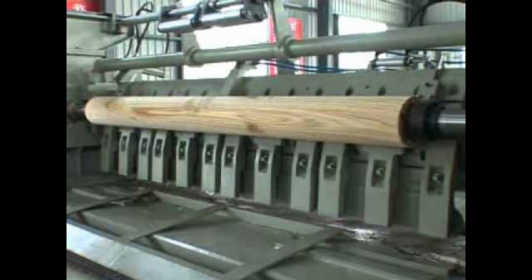There were experiments with gluing plywood with phenolic resins, mostly in the form of an alcoholic solution or powder, which however did not provide sufficient accuracy of application. Around 1930, a dry process of gluing veneers to plywood with phenolic resin in the form of a film began to spread in the production of waterproof plywood. Now let's see some structural characteristics of this plywood.